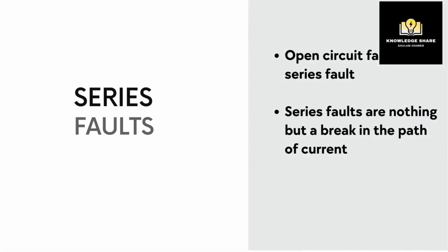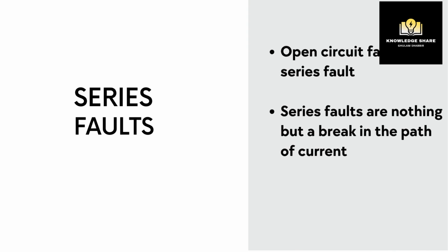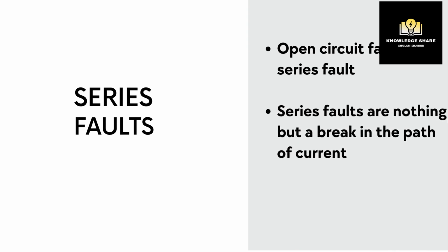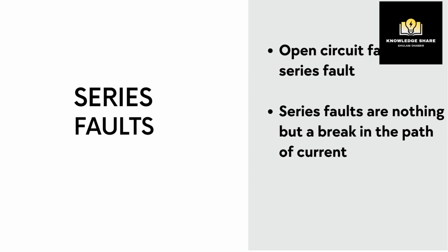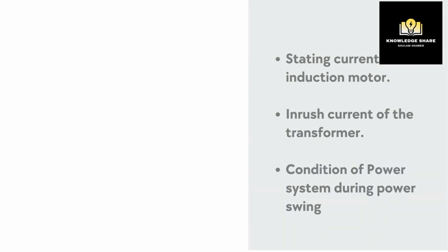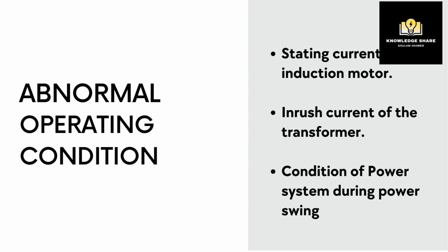Now we will discuss series faults. Open circuit faults are called series faults. Series faults are nothing but a break in the path of a current. Suppose we are using a circuit breaker or a fuse to protect the circuit. If one or two phases open and the third is still in the circuit, such a kind of fault is a series fault.